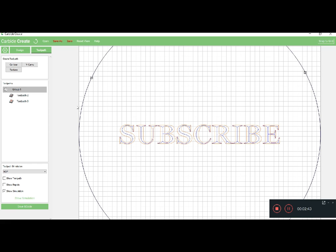And if I wanted to, I could come over here and I could hit save G code. We'll do that here in a second. But let me show you one more thing, and we're going to look at the pocket. Okay, so let me click this. You know what, actually before I do that, let me show you this as well. If I wanted to do the letters first, which I'll probably want to do anyway, we're going to go move up, and that'll actually move that up, and I can change the name to this. So I can just probably hit edit operation.